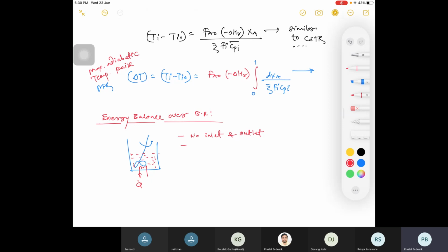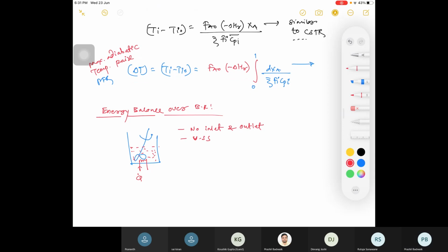If you want limited production and high residence time, then you can go for a batch reactor. So as he said, it is unsteady state operation. Concentration changes with respect to time but not with respect to position. Seasonal production, limited production, I could say, and high residence time can be carried out.